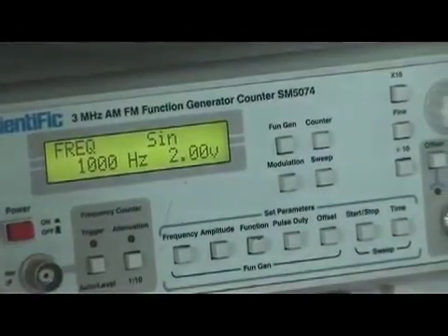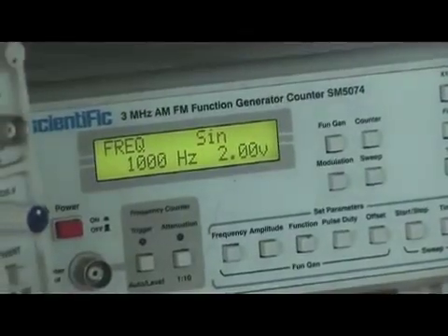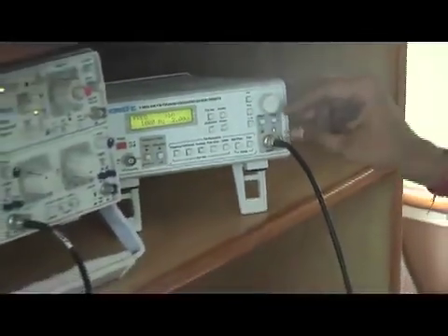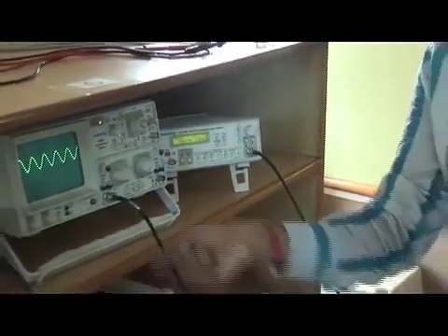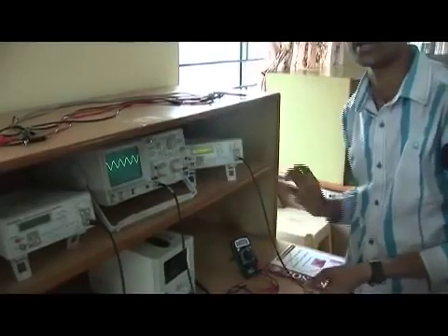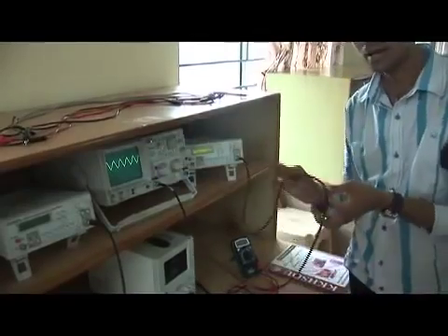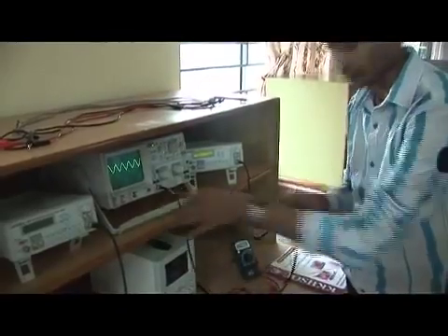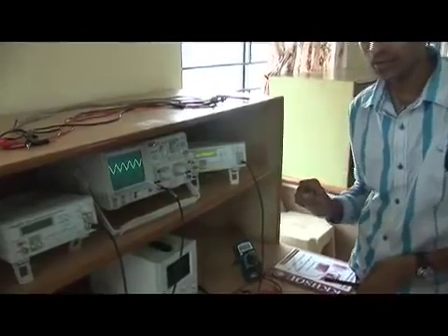Now we are getting a signal having an amplitude of 1.9 volts. So what happened to the 0.1 volt? It happened when you transmit this signal from this wire to this CRO. This wire has some resistance, and wherever there is resistance there will be a voltage drop. Due to the resistance of this wire, there is a voltage drop of 0.1 volt, so that's why we are getting 1.9 volts. But we don't have to worry about that. This is a small error in electronics, due to the resistance of the wire. So this is how we calculate the amplitude.